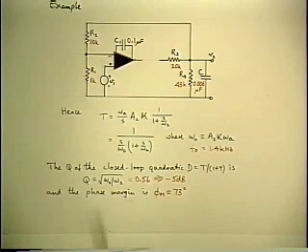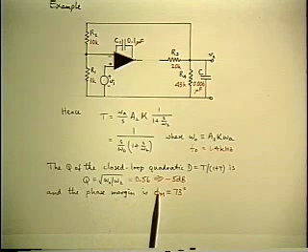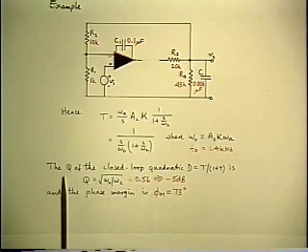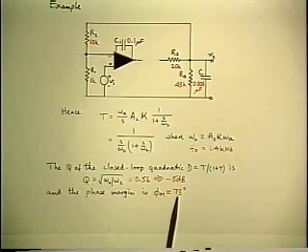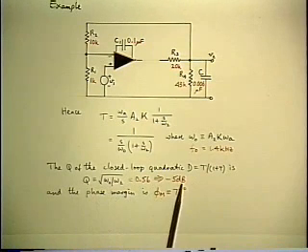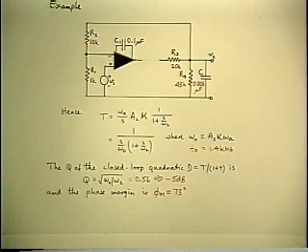It's just a little bit above the break point between real and complex roots. And if you look up in that normalized graph, you find that the corresponding phase margin is 73 degrees, corresponding to the minus 5 dB for the Q factor. Well, probably this is an acceptable phase margin, giving rise to the acceptable closed-loop response.